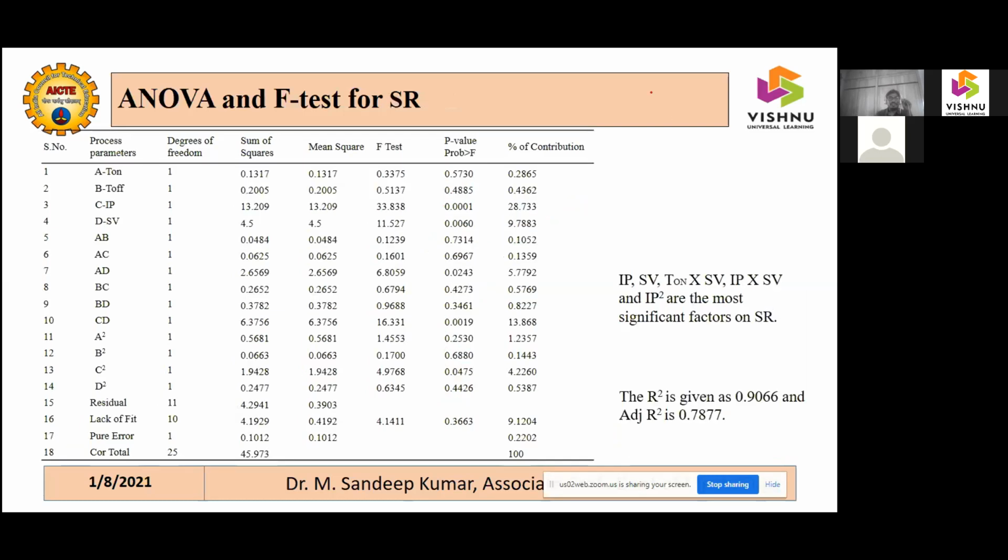Now for surface roughness, the input current is the most affecting parameter. Here the experimentations were conducted well. Generally, when you do the experiment, there is very little chance of a huge variation of more than 0.2 between the R square and the adjusted R square. Because if you have done the experimentation properly, you can get 99%, 99.99%, I can't give more than that. So 90% of the time, the difference between R square and adjusted R square would be less than 0.2.